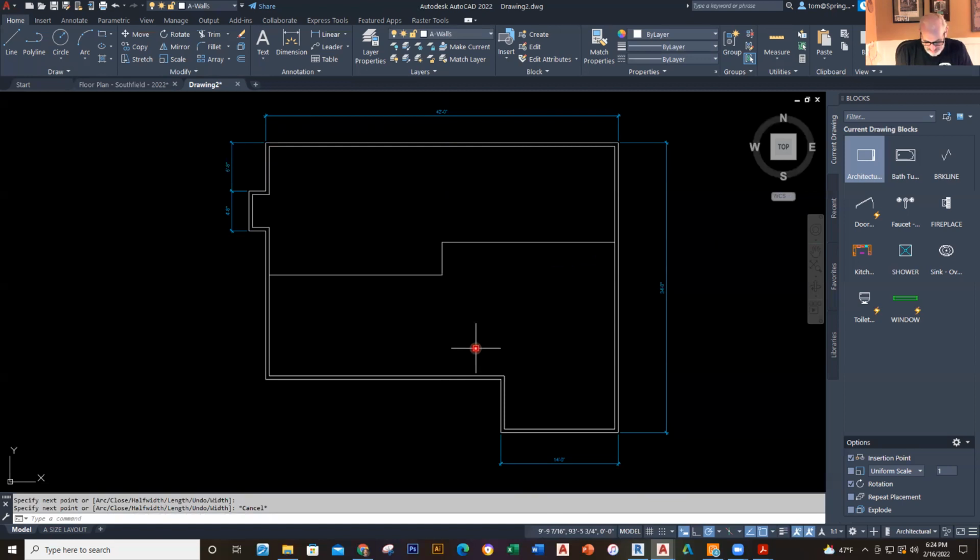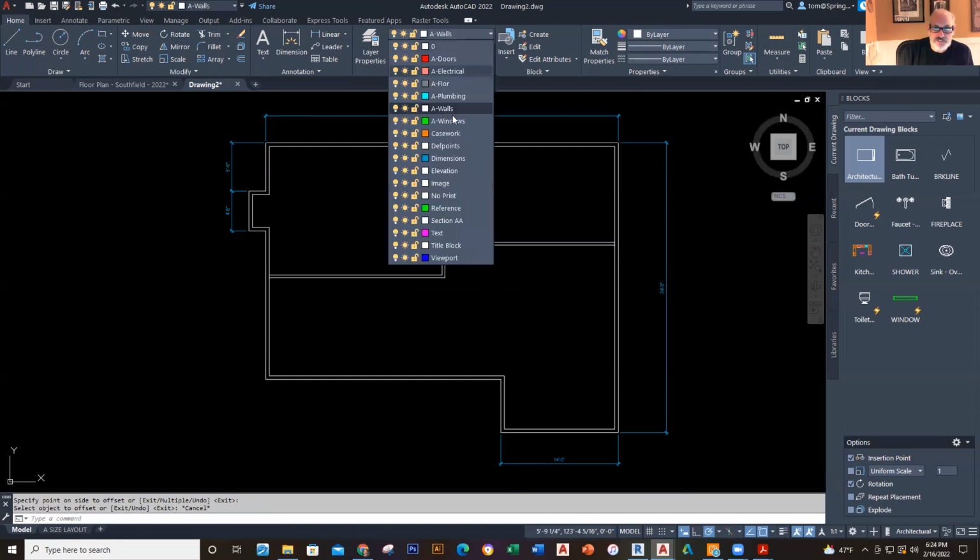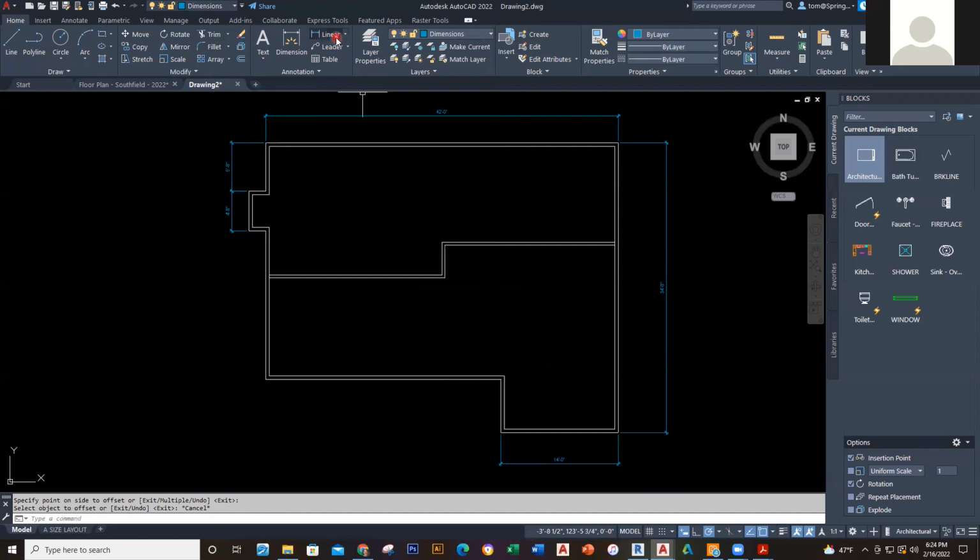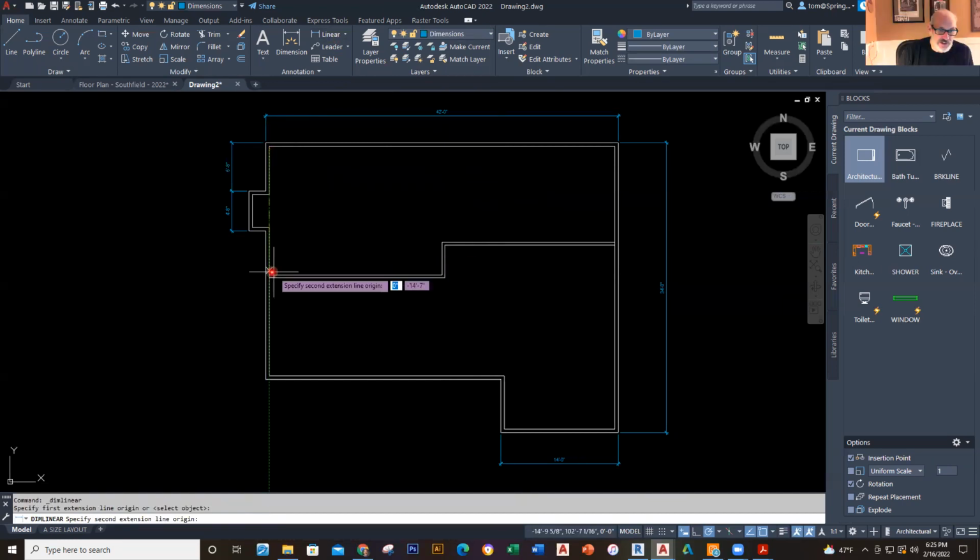Okay, then I'm going to offset this line 4 inches. So I'll go offset 4 inches to give me this line right here. So go ahead and offset like that. Now, once I've done that, I'm going to put a couple more dimensions down, make sure that I am where I should be. So this is all about checking it and making sure that your particular project is accurate.